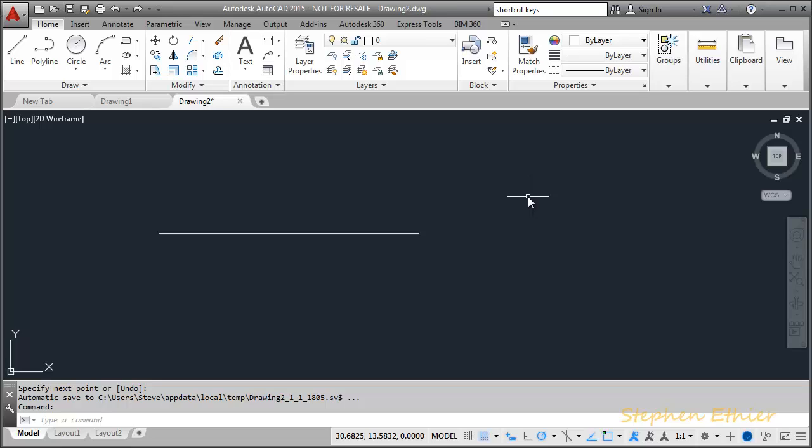The last toggle button to review at this time is the Object Snap toggle. This is one of the most important options to get used to, as you'll use this often. Simply put, when the object snaps are active during drawing or modifying, the cursor will snap to preset locations on an existing object that you hover over. Make sure that the object snap is turned on, showing blue. As you can see, it's on now. I pick on it, it's gray. Pick on it again, it's on. So we want it to be on.